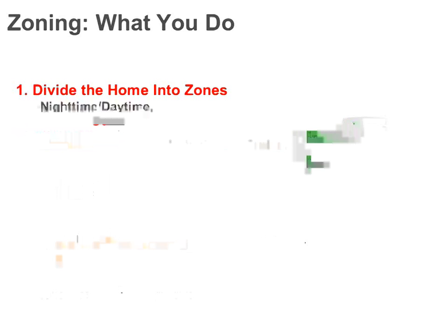You may want to zone it differently a little bit based on the orientation, right? Especially if you have rooms that have a lot of glass and are going to get a lot of solar load on them, right? So you got that family room that's got that solid glass wall overlooking the lake. Lucky you. That room probably needs to have a different thermostat than the other side of the house that has hardly any windows whatsoever and a different sun exposure.